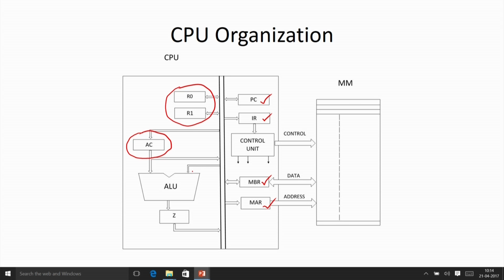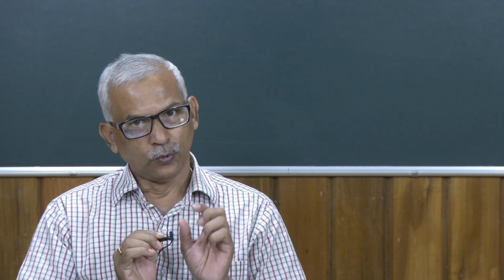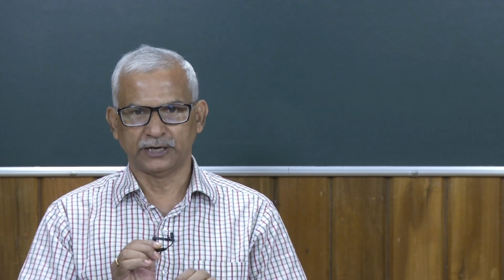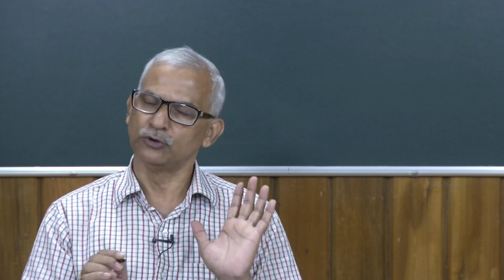After performing the operation, we store the result in some register Z, which is a temporary register, not visible to the users, and from Z we store the result in the accumulator. So, the effect of these things is that accumulator becomes accumulator plus R1, maybe taking from register R1. So, in an accumulator-based processor, what we generally do is use the accumulator register to accumulate our result, and after performing any operation the result will go to the accumulator.